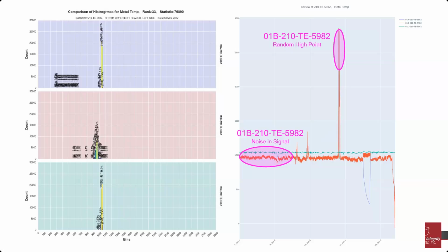But in order to offset that trade-off, we added a backup thermocouple to every location. You heard Kane mention we had to swap over to the backup in a couple of situations where the primary might have failed or didn't have a good attachment. So I just wanted to mention we built that into our project plan.